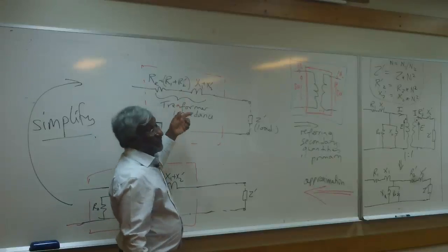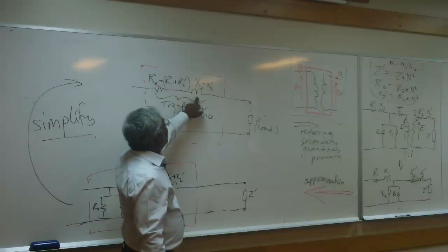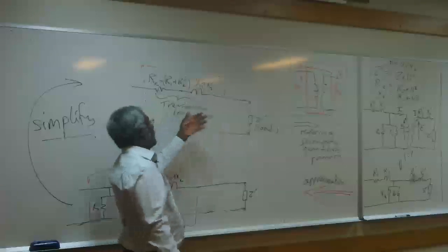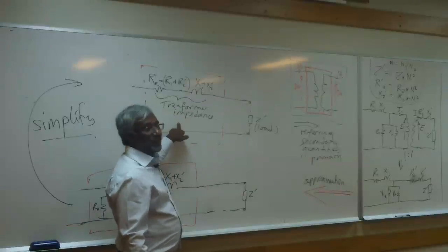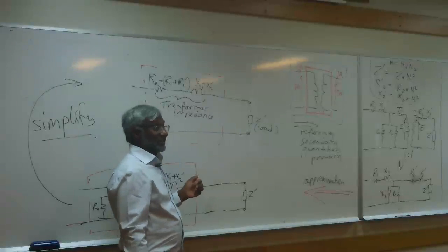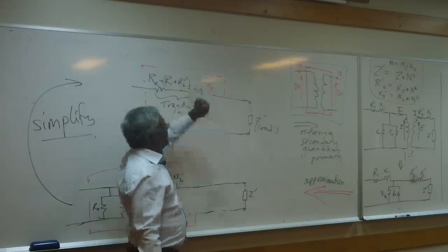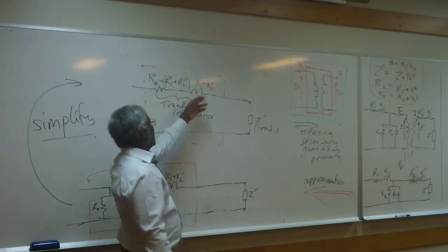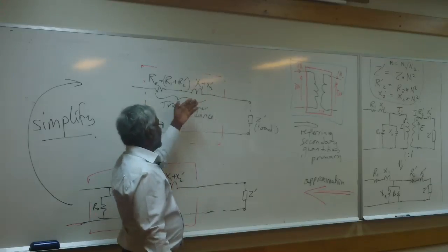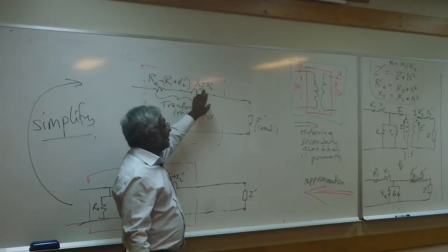You may have a correction factor if you're worried about skin effect. And that one you can get separately if you wanted, by taking it away from the impedance you get by doing the short circuit test. But most people don't get that separately. They just assume that it's approximately equal to Z, because normally R is much smaller than X.